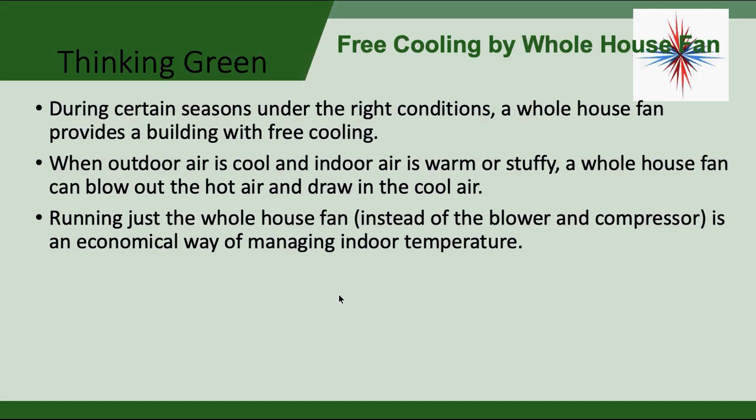It's part of the building control system. We use what's called an economizer, and you'll talk much more about that in your air conditioning term. It basically allows me to pull in that cooler outside air, and I just continue to do air exchanges throughout the entire building.